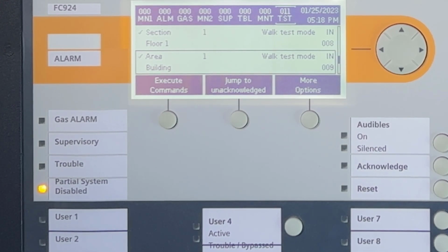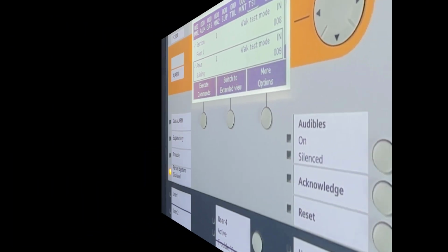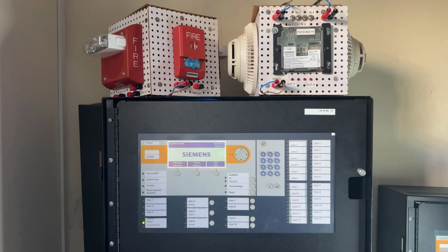One of the benefits of setting the panel to the appropriate test mode is that the detectors being tested are set to their highest sensitivity. This makes a difference in time and amount of test gas applied to activate the detector. A test mode setting also makes it much easier for one-person testing, as there is no need to keep pressing the acknowledge and silence commands.